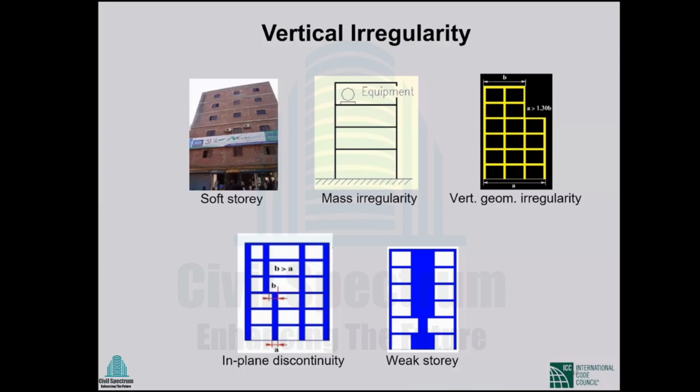So brick walls are actually very stiff. They are quite weak in terms of strength, but they are quite stiff in terms of stiffness. So they may be broken quite easily, but it is difficult to deform them with unit amount of force. So that is the definition of stiffness. So if a story is devoid of any brick walls, whereas the adjacent stories have brick walls, then the story without the brick walls becomes soft story.